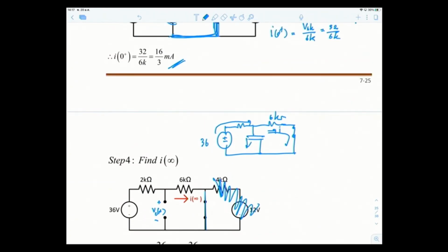This current I, where does it come from? Well, we have one source. So therefore, current goes like this. As I said, always find out how the current flows. Let's call it I total here. It goes through 2K, comes here because the capacitor acts like an open circuit, passes through 6K, goes down the shorted path and back where it started.